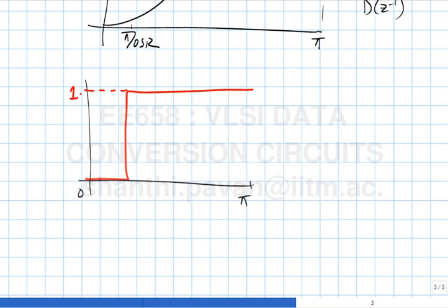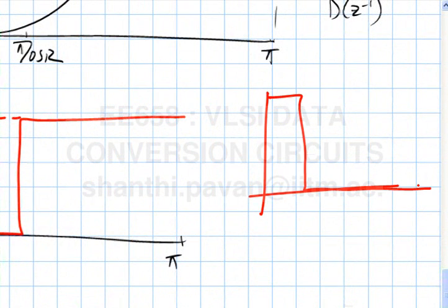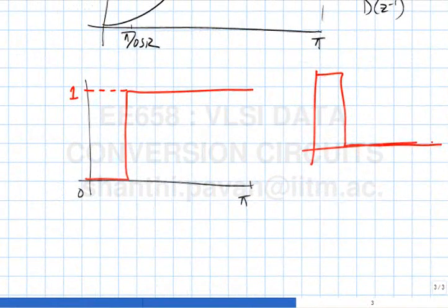So the analog high pass stuff is again a frequency transformation of the analog low pass filter. So people have spent a lot of time trying to approximate, how to realize the characteristic of this form. Once you're given a low pass filter transfer function, you can derive an equivalent high pass filter transfer function by what are called frequency transformations. At least you must know that given an analog filter transfer function, I will be able to use the bilinear transform and get a digital filter with the same shape.